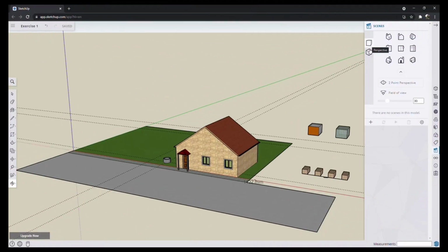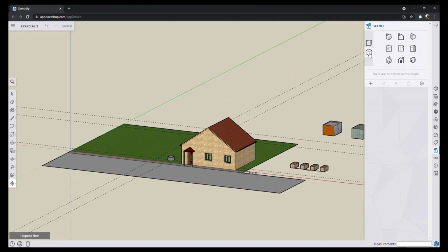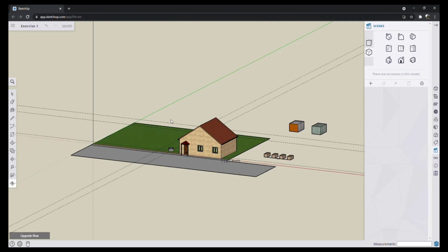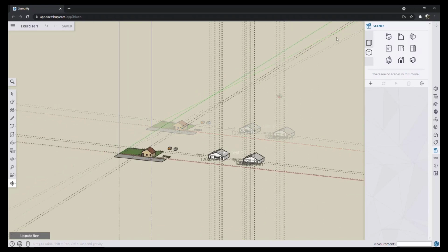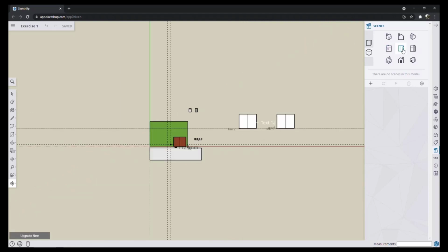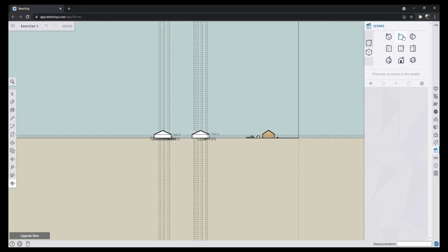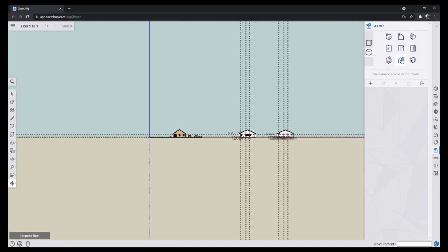But it's okay, I can change to a parallel projection. And now, all those views will be exactly like in AutoCAD. So if I want to use a 2D perspective right now, I can use a plan view, for example the top. And now, this is great if I want to draw only 2D objects. And the first 3 exercise files that I provide along this tutorial use this view. So don't forget to download them if you haven't done it yet.